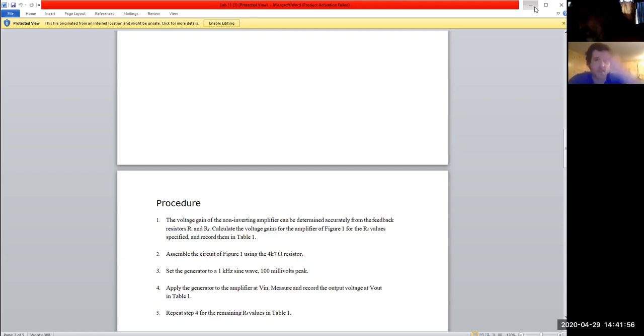But like in a soldering pot or wave solder. Oh no, I can hand solder surface mount. Nice. I can't do that. Well, it's a trick, but you need more than one soldering iron. Yeah, so surface mounts usually sit on a square pad, right? They've got the four sides to it.